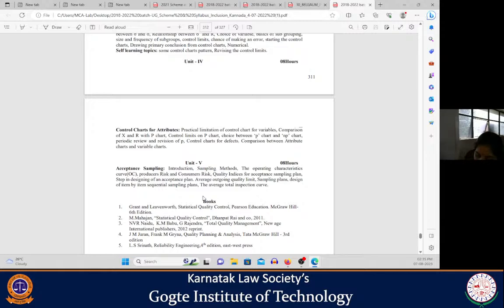The quality of this designated sample will be viewed as the quality level for that entire group, whether it can be accepted or not. Or if there are 1,000 products, then out of those 1,000 products, you will just take 10 or 20 products, and based on that you will make assumptions for the remaining 600, 800 products. That is, you will decide whether the product is acceptable or not.